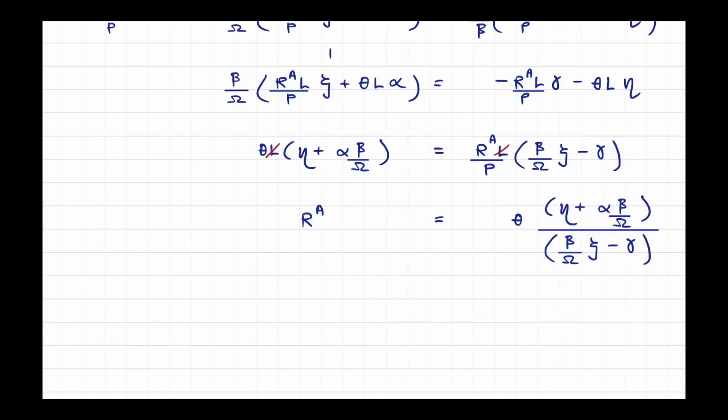What else? You have the P, right? Theta multiplied by P multiplied by eta and alpha and so on, divided by these things. Okay, and then from P we don't want to keep this shape P like this. If you recall, K square is equal to P over EI.